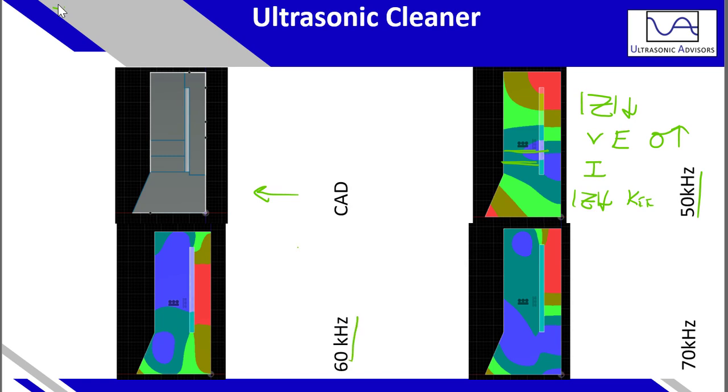So here's a resonant mode at 60 kilohertz. Again, you can look at the dark blue areas as higher stress regions. Here we have a significant displacement occurring, because these are all displacement simulations. In this specific area, you have large displacement occurring in the center bolt, and here you have the center bolt expanding outwards.